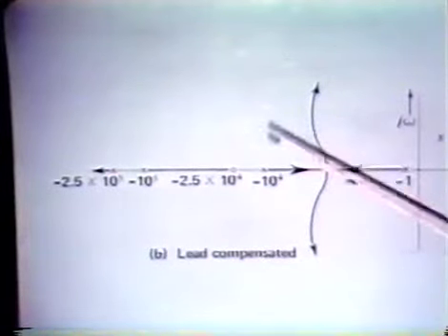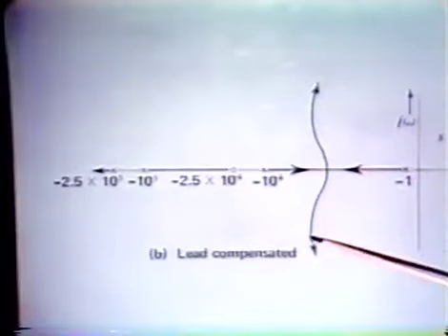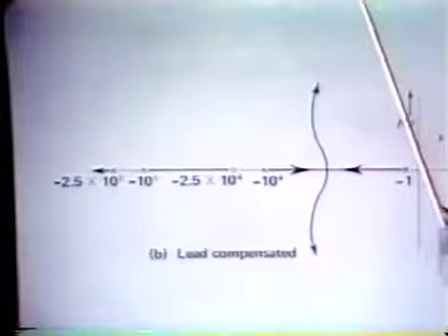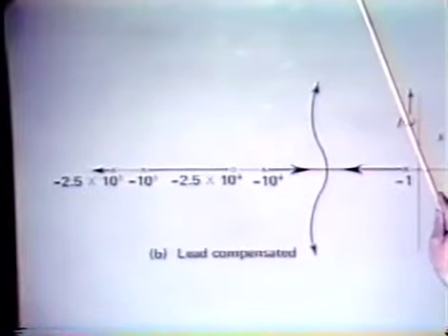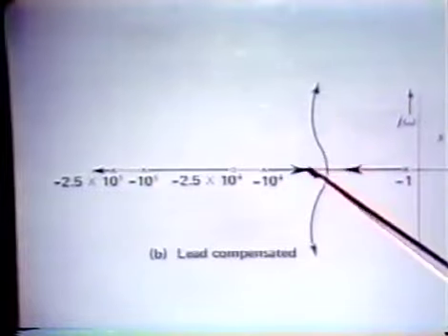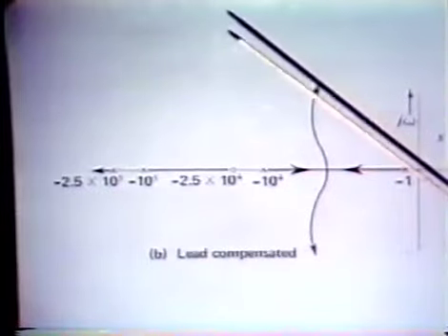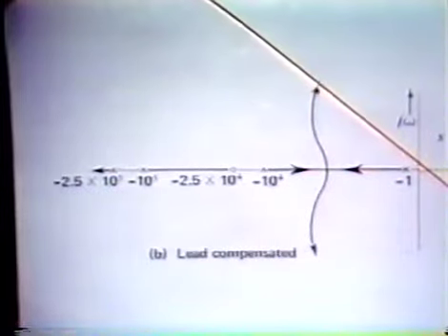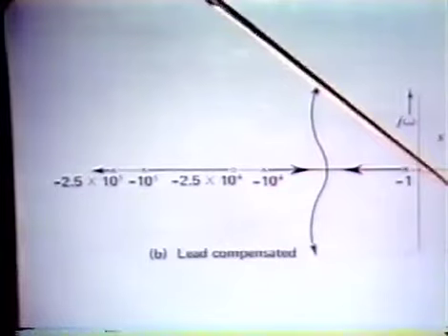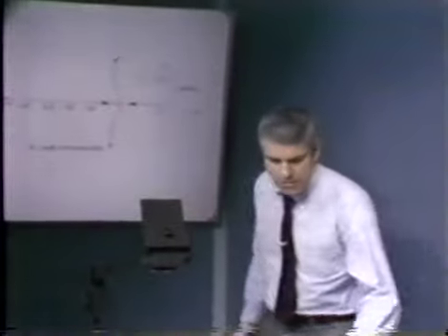And if we keep track of that, we find out basically that we can tolerate considerably larger values of A0 F0 before we get to a given damping ratio for the dominant pole pair. So here, in our particular system, if we kept track of how far out on the root locus diagram we had gone, we'd find out that we get the much better damping ratio with the lead compensated case than with the lag compensated case. Or, I'm sorry, with the uncompensated case.